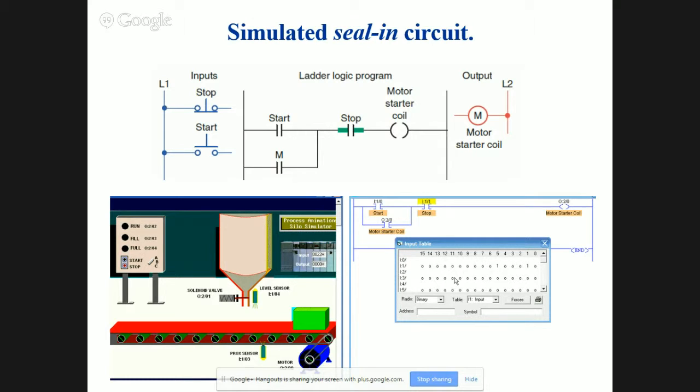Most control systems, we talked about feedback from the contactor. That'll just be for alarming. There'll be an alarm bit in there. You'll probably still use the seal-in because there is a mechanical action time delay from when you fire an output. The PLC will pick that up and you'll get false alarms. So basically what you'll do is you'll tell the motor to latch in maybe for half a second. And then if the motor's been told to latch in and you don't get feedback within half a second, you'll sound an alarm and shut the motor down.